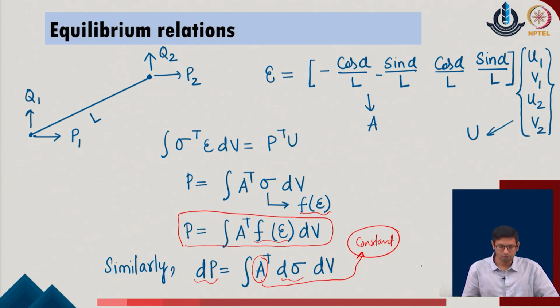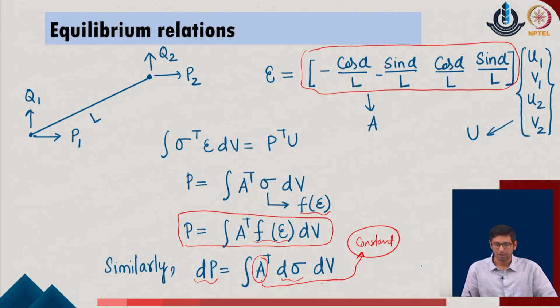Once we know the relationship between the force and the internal stress component, to define the small incremental changes in that, we not only go with the change in the stress component but also change the A component. We are not replicating that point again over here, but with the constant value of the A parameter adopted here, the expression will make sense for now. But if you are also adopting geometrical nonlinearity in the given system, you have to adopt the variation with respect to the A parameter as well.